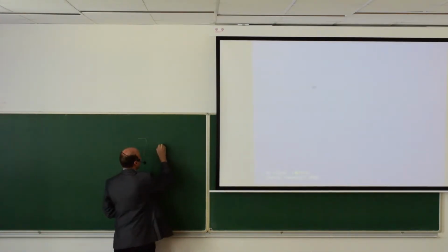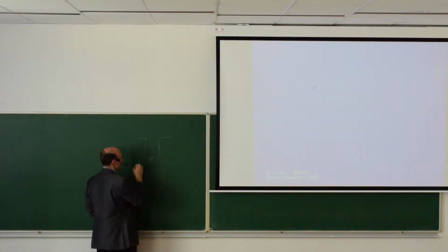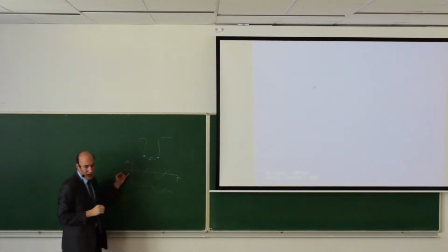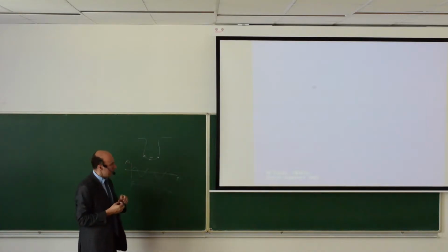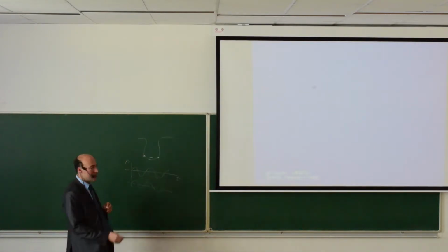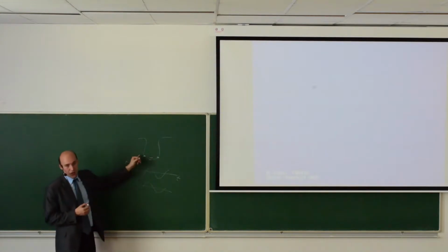Because if you have this shape of tube, so looks like this, then we have this driving mass here and the position sensor is here and here. Then the signal that we will see from those sensors, this is time and this is some amplitude of the motion. So then when there is no flow, you will have zero phase shift. So we will see two signals. But you can measure also independently the density of the liquid that is inside the tube.